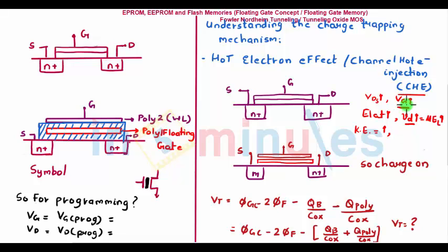And we know that gate voltage was very high. I beg your pardon, that was a part of another electric field in MOSFET, which was given by VGS by TOX. So as VGS increased, we know that it used to attract the electrons towards itself. Some electrons will move there, but some electrons will get trapped in the oxide layer. This exact phenomenon we will try to achieve in the floating gate. The electrons which were trapped in the oxide, that is what we are trying to understand. Some electrons will move towards the gate, but some electrons might get trapped.